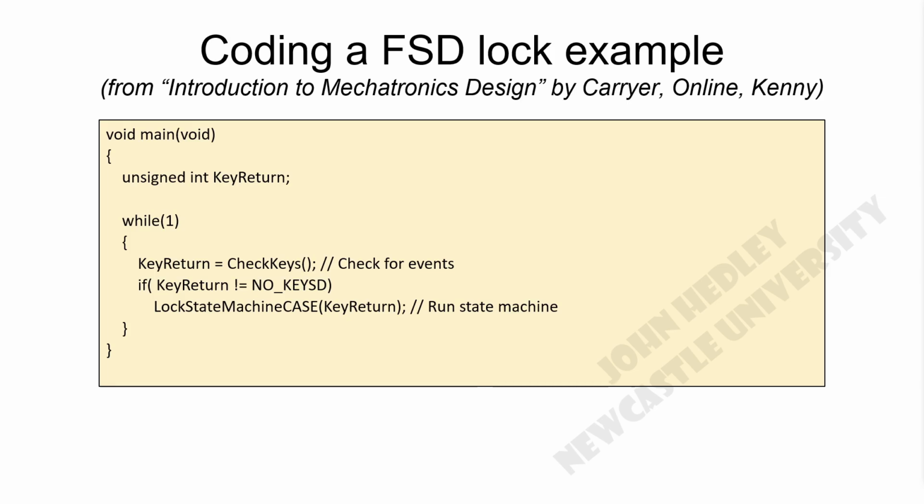This part of the code is the main program. You can see that the program just runs in an infinite loop with the while one statement. Within this loop, all the program does is check for an event, i.e. it is event-based programming. On registering an event, the if statement, which is only true if a key is pressed, is activated, which calls the service routine.